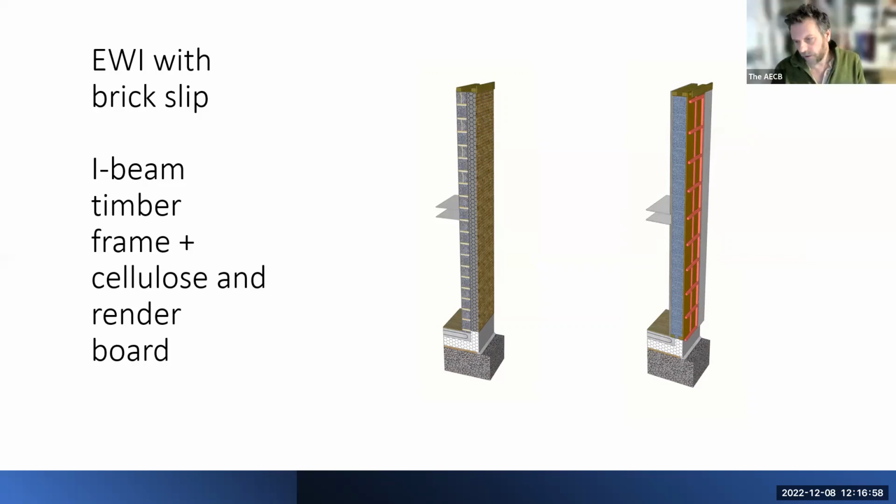It's interesting this because we did end up with quite a nice low carbon timber frame wall version of this, sort of cantilevering off that reinforced concrete slab there. But on some projects I still hanker for that solid masonry inner load-bearing element, and putting something on the outside of it because of the ease of fixing and the simplicity of the construction, the lack of layers and so on. So I don't feel quite ready to abandon some of these things, which is interesting.